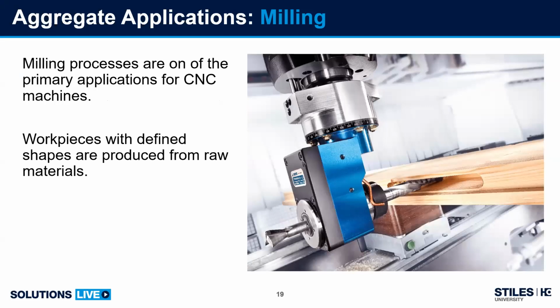Getting into milling now. Milling, another large application area for Benz. Milling processes are one of the primary applications, honestly, for CNC machines. You can see this is a great photo here of our Forte head. This is doing a lock recess. As you can see here, we actually have a little bit of offset on this unit, so you can load that up with a little bit longer tool, so you can plunge into the material at a greater depth.